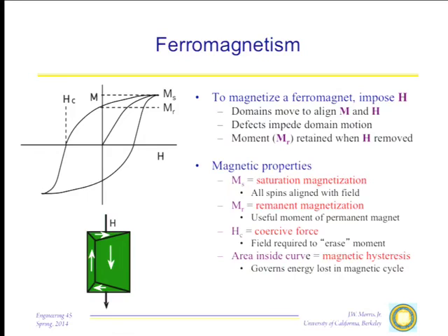So that's the coercive field. Then of course, if we want to reverse the field, we can reverse it to full saturation, but we have to push the field even further to cause that to happen. And if we were to then reverse the field again, we would generate this loop. This loop is called the hysteresis loop.